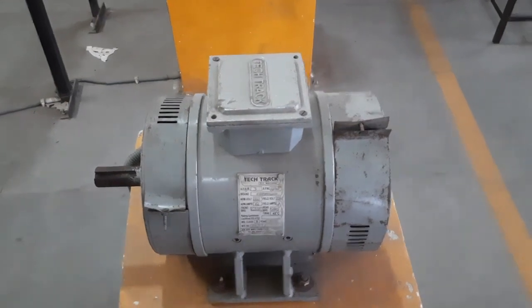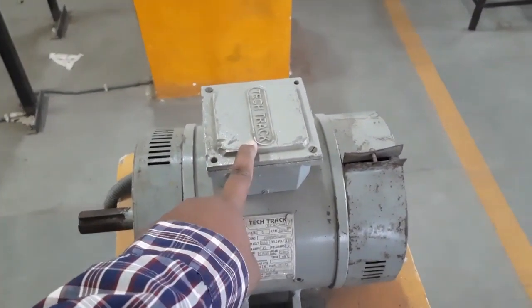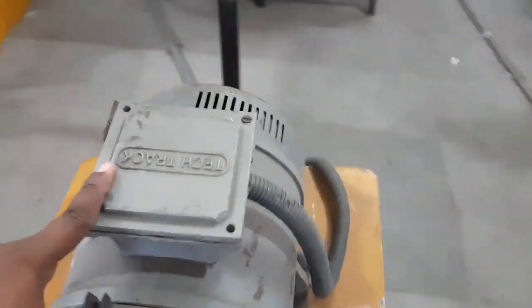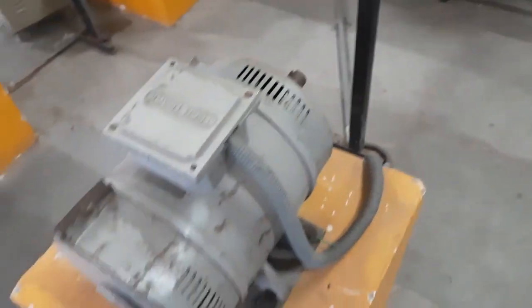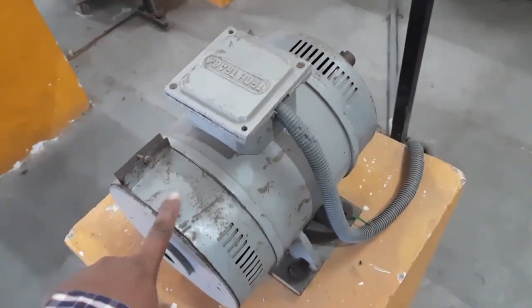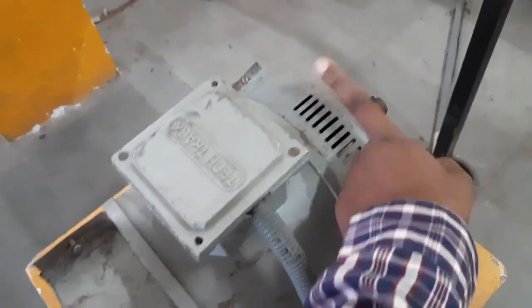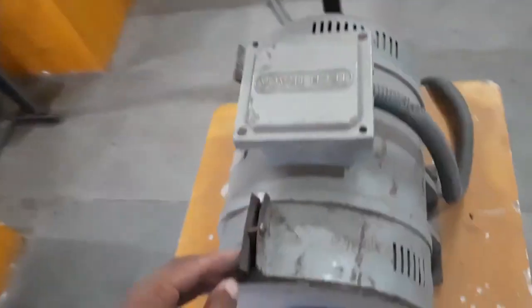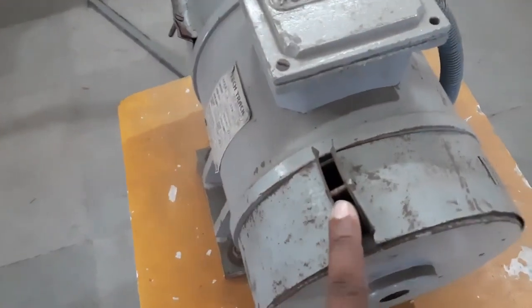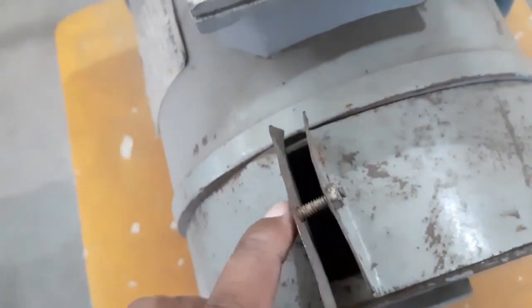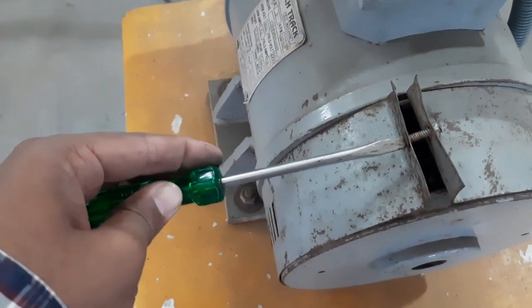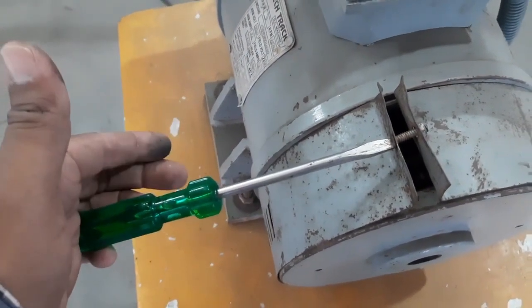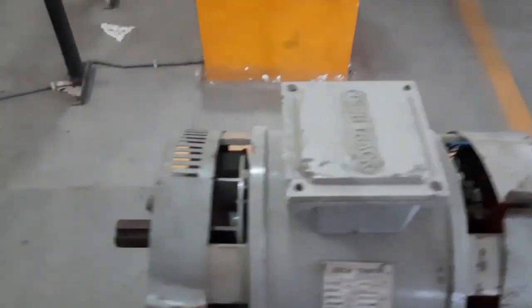Now this is the part where the connections of the DC generator are made. As you can see, these connections are going out of that box and to the generator panel. Now we have to remove these two rings that you can see. We have to remove this screw, as you can see in your picture. This screw we have to remove by using different types of tools. You can use a normal flathead screwdriver in order to unscrew this particular bolt by turning it clockwise. Now you can see we have already loosened these two rings.